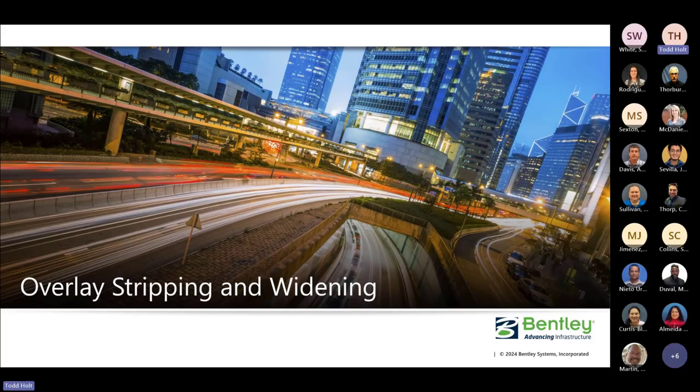So we might have a triple R job. We're going to mill down 3 and we're going to put back 3. Or we might need some different adjustments on that. So we're going to look at those two overlay and stripping components and how we set those up. And then we'll run through a couple of different examples. I'll probably bounce back and forth between the PowerPoint and ORD live demos. I do have a couple files open in the FDOT workspace, but we'll get into those.